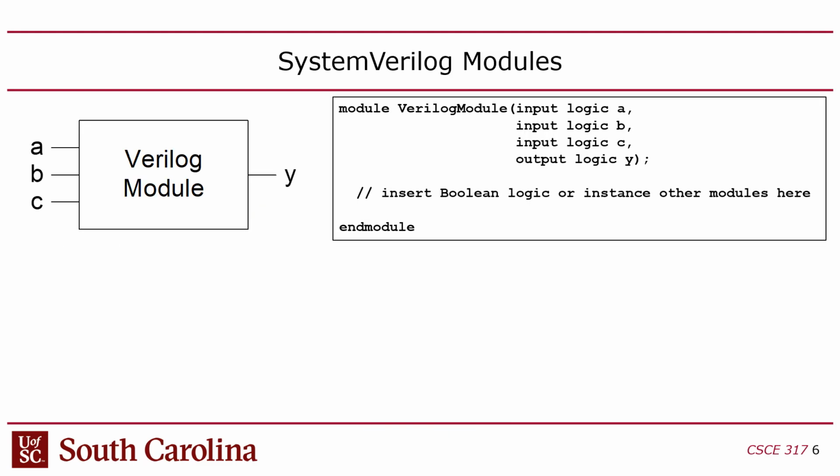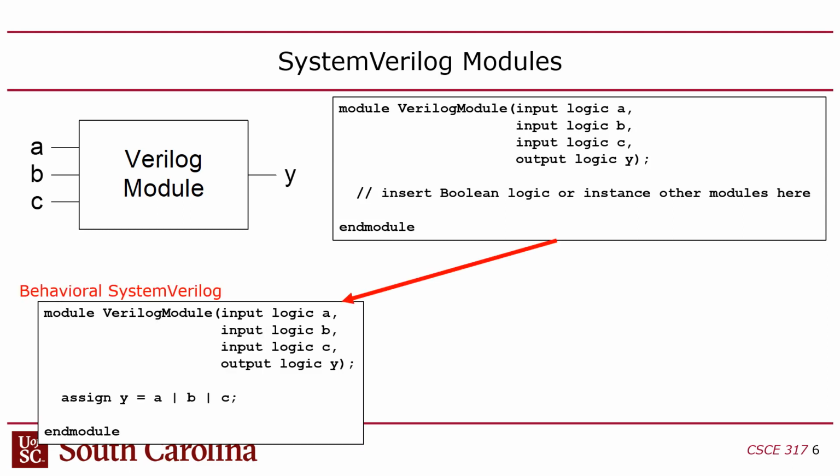And so you've got Verilog modules, which you write with the module line at the top with the top level IOs. You put the implementation in the middle, and then you put endmodule, right? So you can have behavioral Verilog. What constitutes behavioral Verilog? It's basically two things. The assign statement, which is basically just Boolean algebra. You can put arithmetic in there too, like multiply and add, and then the compiler will generate an adder circuit or a multiplier. You can even put a divide.